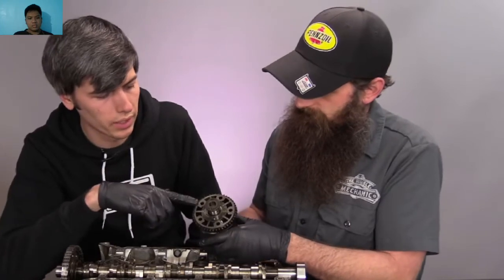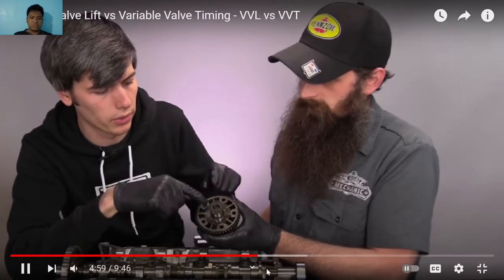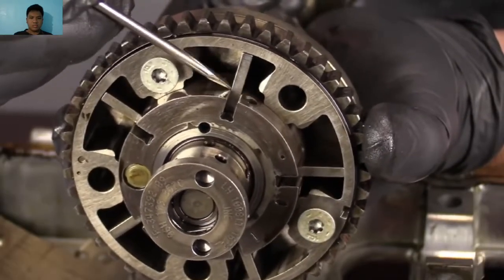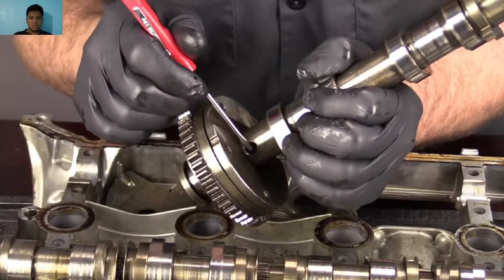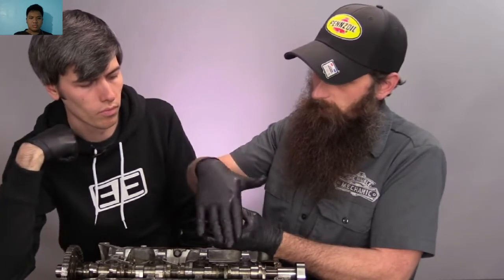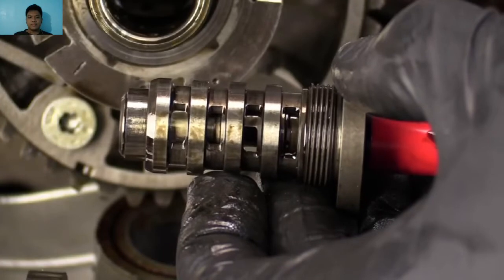Cool, so you've got this little complicated chamber that's sending out oil, and all you're doing is filling either one side with oil or the other side with oil. They both have a port, and then you can drain it out the back there. That's it. It's all controlled. On the timing cover, which goes in front of this, there's a solenoid that goes there. This is a spool valve, like you said, that has different chambers and ways to...